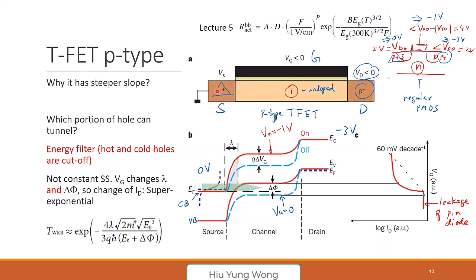Okay, but what we are talking about is across this cross section, right? Let's say we have a perfect interface. Okay, no traps. Are there traps in the body, in the bulk? No traps. Perfect. Everything is perfect. And in this device, tunnel FET, we don't want to have traps. If you have traps, you reduce the subthreshold slope. Okay. But tunneling is still playing a very important role.